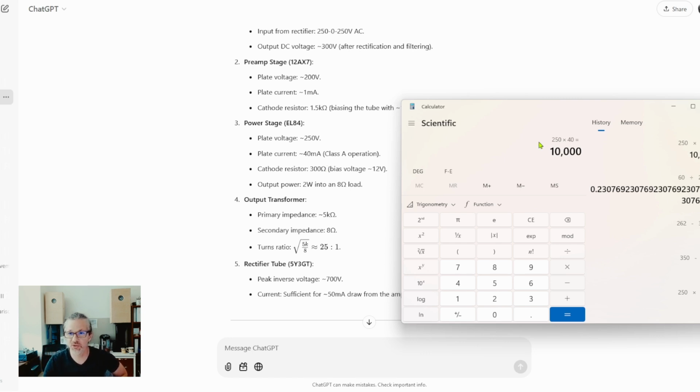At 320 volts, actually for this tube, that's a little higher than the maximum recommendation for the tube. Let's see, 320 volts with the same cathode resistor, probably it will be around 45 to 50 milliamps plate current. It will bias there, let's say 46 milliamps, and then it's almost 15 watts of plate dissipation divided by 12.